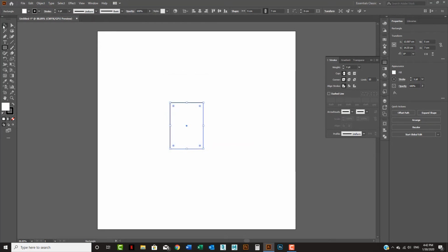And always when you're drawing something, you can press V to go back to the selection tool so you can move your shape around. So here we go. This is the actual face of my Advil box. I have four sides of those. So I'm going to hold Shift and Alt and click drag to the other side, and I'm going to have one copy.